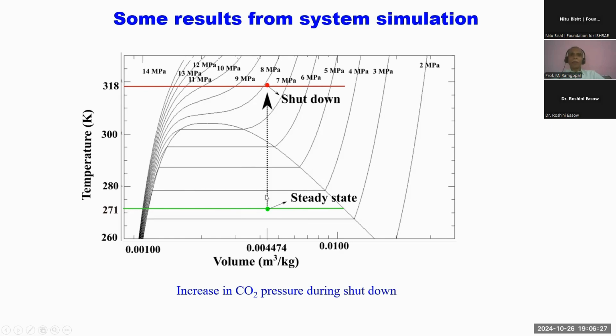In our case, what we have done is, even though our operating pressure is about 32 bar, we have designed all the components to withstand a pressure of about 125 bar. So even if the system is off, and it reaches a pressure of 80 bar or so, it can still operate without any problem. I mean, there won't be any bursting of the tubes, etc.